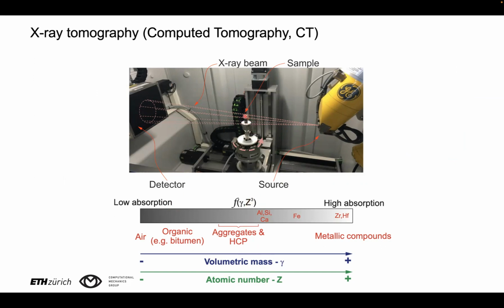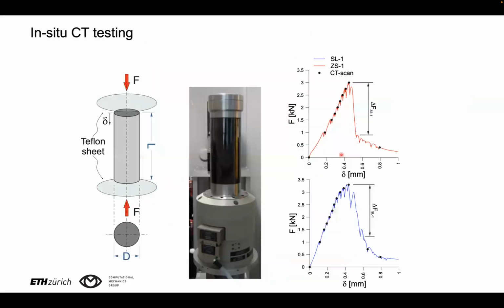It should maybe also be added that each scan through the specimen will give rise to a 2D image, but then the specimen will be rotated inside the CT so that at the end we will have a collection of a large number of 2D images. So each of these 2D images is a radiography. But the collection of all these 2D images will be reconstructed into a 3D geometry through image processing algorithms. And so at the end of this test, we will have a 3D visualization of the heterogeneous specimen.